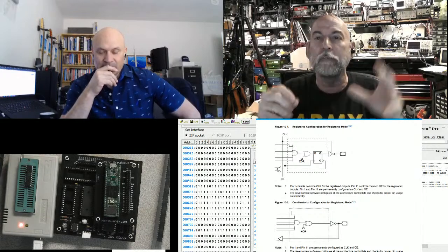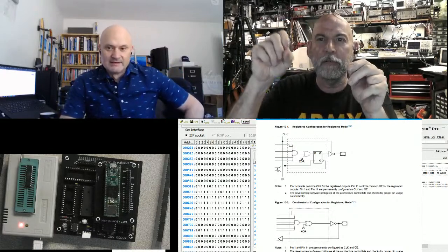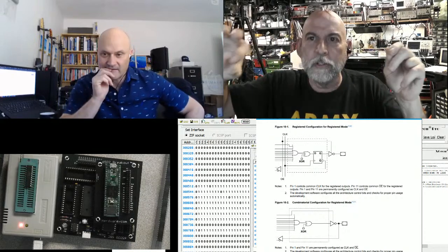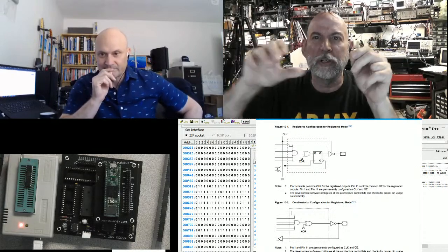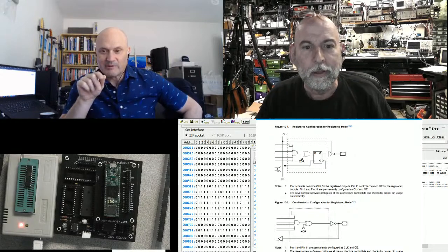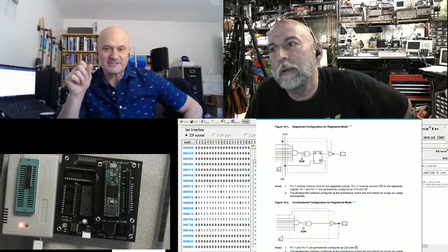And if the clock is changing frequency, so can I. Because basically, when I get a phi rising edge, I do all my computation. The clock falls, I do all the computation, and I do it in 1/32nd the time that a normal 6502 takes. Right, but based on what you just said, if you wanted, you could do it in 1/68th of the time.